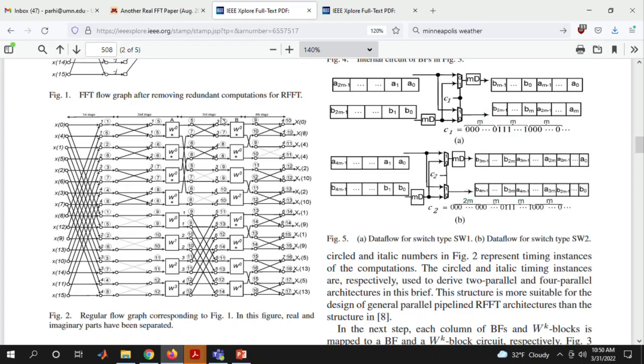shows the clock cycles, just like what we have gone through in the complex case. It shows when there are available clock cycles 5, 7, and this butterfly is executed at 7. But it also shows the control bits, the control bit patterns, M zeros followed by M ones for that M delay switch delay. That's what Nanda was explaining to you.